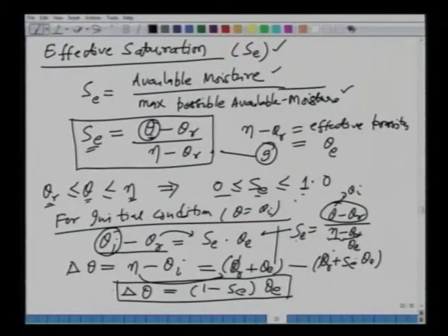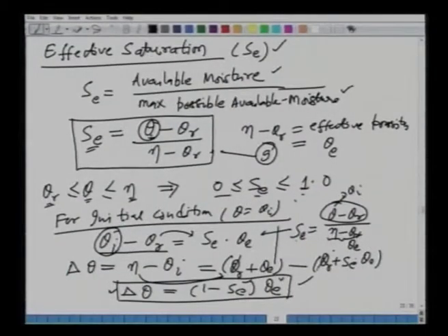are analyzing the infiltration. And then we wrote down an equation in terms of delta theta, the effective saturation, and the effective porosity, okay, because theta r is something which cannot be replaced just by gravity forces. All right. So, for all practical purposes, if we have the values of theta r, this is the equation which normally should be used because it accounts for theta r.